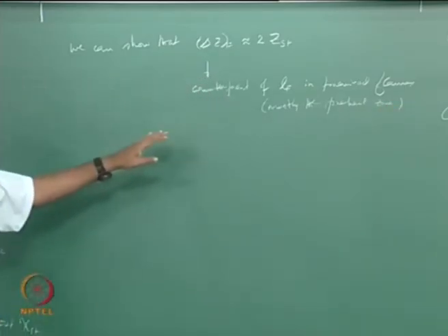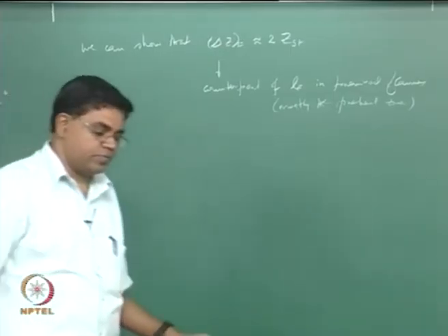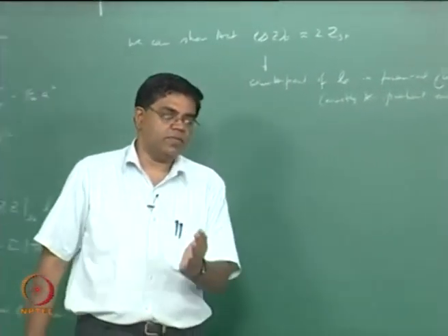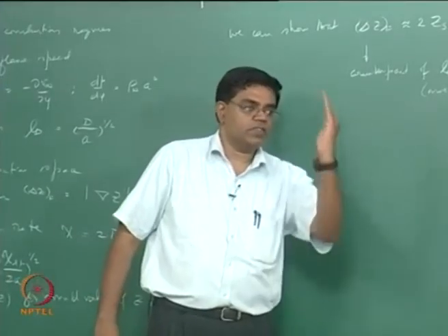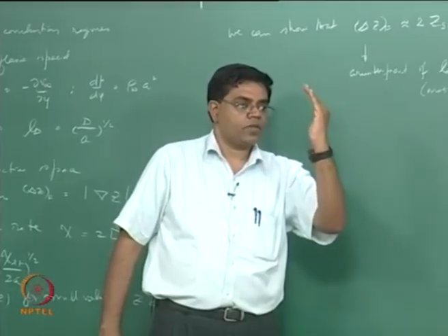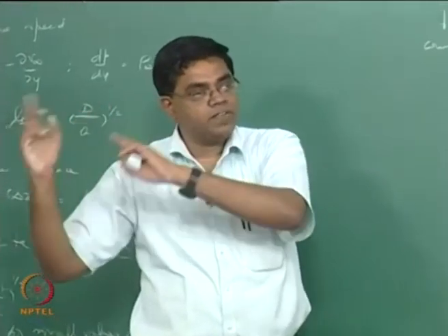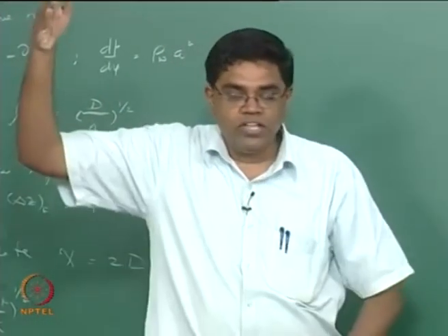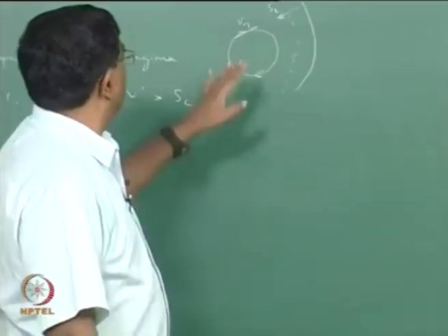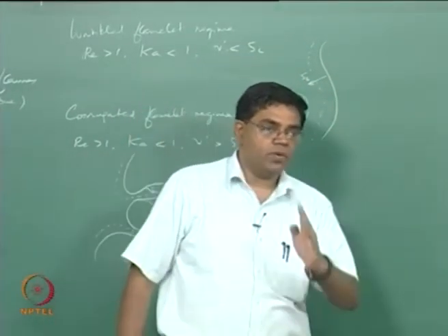And we did point this out when we were doing diffusion flames, if you recall. So when we did the laminar diffusion flames, what we pointed out was the Burke-Schumann assumption was essentially saying that the flame is a sheet along the stoichiometric surface, but that was essentially the reaction sheet, right. So it's sort of like saying in the premix flame, if you now think about only the reaction zone as a sheet, but consider the thickness of the preheat zone, like the way we have been drawing pictures here, right. Then what happens in the Burke-Schumann problem?